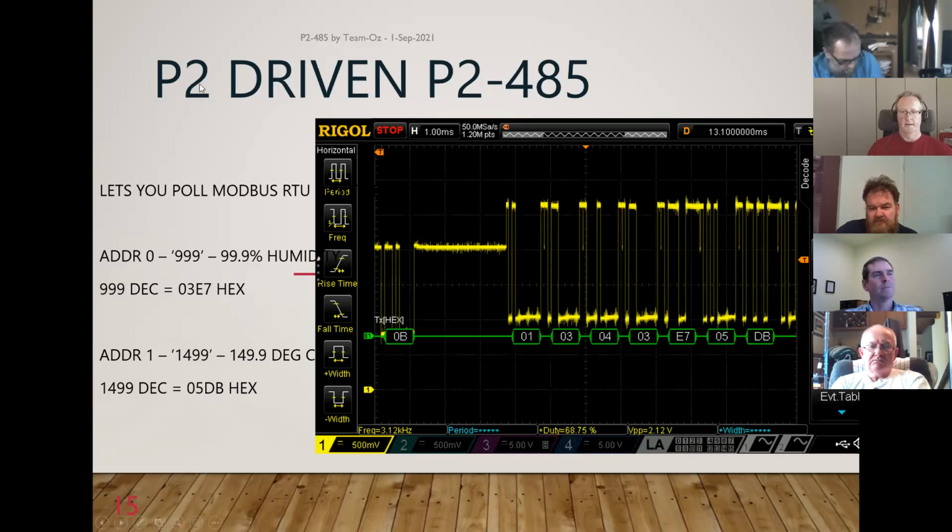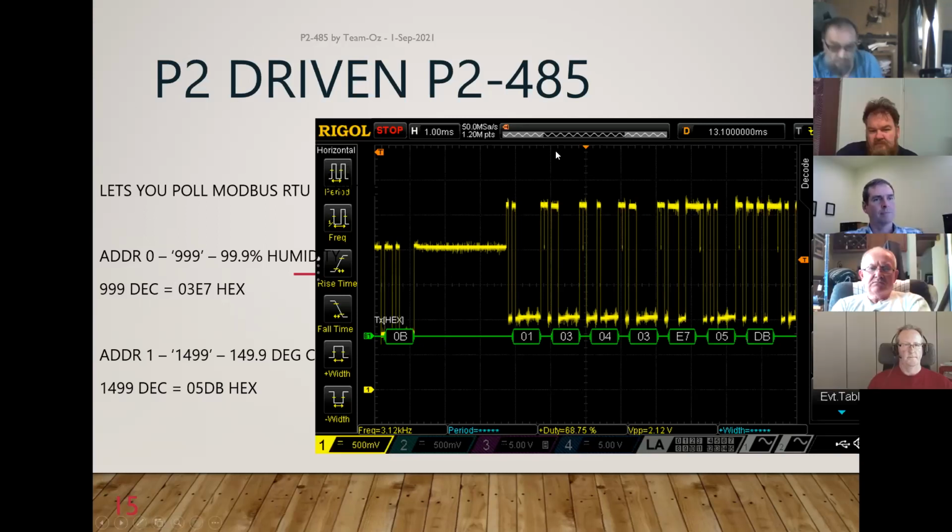Modbus is really easy too, in that it's a half duplex situation, and the protocol defines the timeout period. If you do a request, you expect something to come back. In Modbus, you may have just a command sent out or a global value that doesn't require anything. I did a Spin driver with an assembly driver and a Spin interface for Modbus a long time ago, and it turned out quite easy. Given the capabilities of the P2, it would be even easier now.